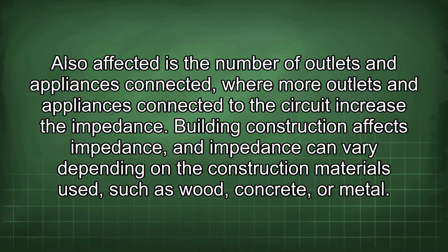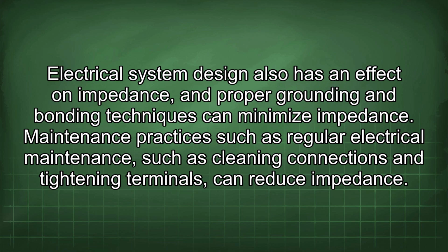or metal. Electrical system design also has an effect on impedance, and proper grounding and bonding techniques can minimize impedance. Maintenance practices, such as regular electrical maintenance, cleaning connections and tightening terminals, can reduce impedance.